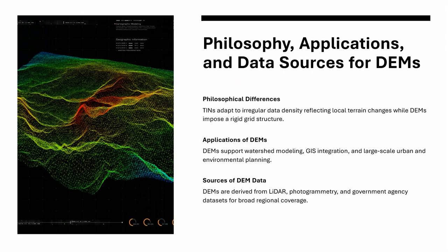So why do DEMs matter so much in survey engineering? That's because in survey engineering, many of the problems we face will be regional, statewide, not just site-specific. Take watershed modeling. DEMs are the foundation of hydrology studies. By analyzing how water flows across thousands of grid cells, engineers are able to trace exactly where water should drain, where basins are likely to form, and how floodplains will most likely develop.